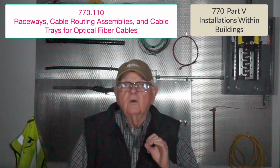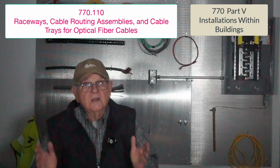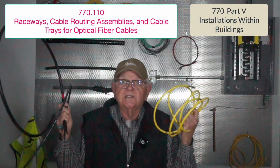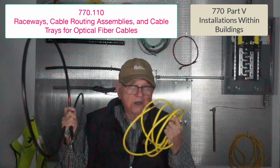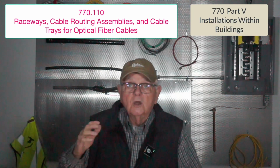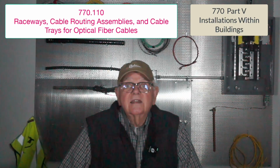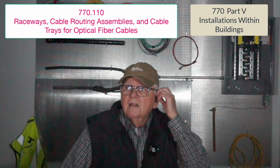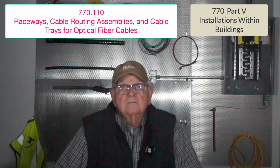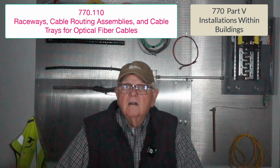Now, 770.110 talks about what types of raceways, cable routing assemblies, and cable trays. Well, we can put this fiber optic cable in any of our raceways that are back in Chapter 3. We can put it in cable tray. In fact, if we go to Article 800, which is our general requirements for communication systems, we're going to find that there is a listing, a big table, that lists all of the different cable routing assemblies that are approved and can be used for this fiber optic cable. So that's in Article 800.